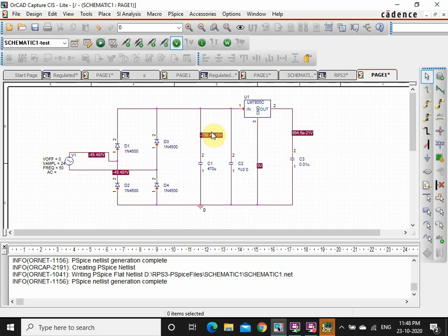Now what we are going to do is select the voltage differential marker. Place your marker here 1, here 1. Once it turns green, that means you will be getting an output at that point. So here this is your marker and this is going to be your marker there. So this is your output. Green color indicates your input waveform and red color indicates your output waveform.